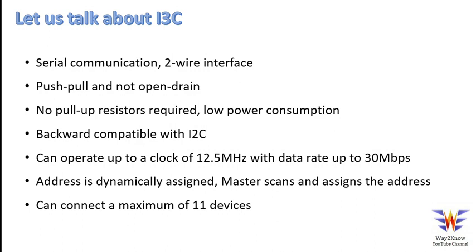And then definitely this is backward compatible with I2C. That means if you have slaves which are I3C, definitely they can switch back to I2C, and basically the backward compatibility is maintained. Now we have talked about the maximum clock frequency of 5 MHz there. Here the I3C can operate up to 12.5 MHz and the data rates up to 30 Mbps.